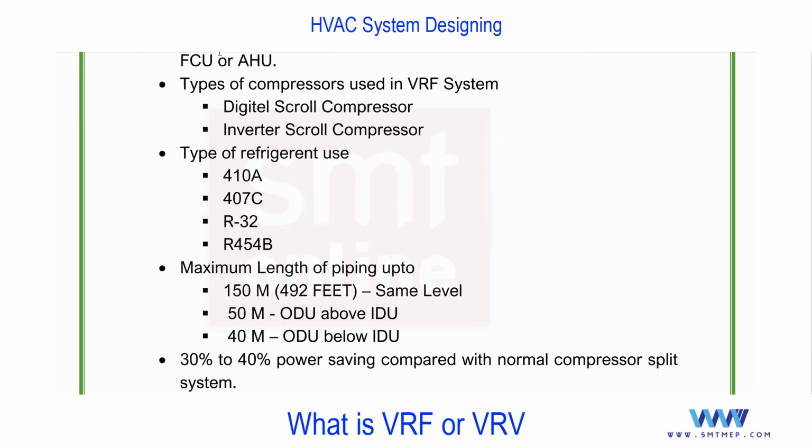You know in a split system, the maximum length of the pipe between indoor and outdoor we discussed is now 25 to 30 feet. Or for some manufacturers, as per the capacity, it may be up to 15 meters. 15 meters is nearly 45 feet.